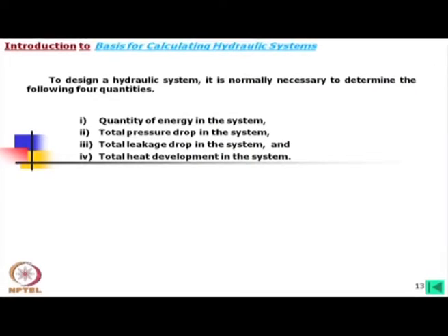Usually, while we are thinking of any transmission system, we should look into efficiency because that is most important. Unfortunately, a fluid power system has lower efficiency than pure mechanical or even electrical systems. The question is, why do we still use fluid power? It has many other advantages, because particularly you can handle a huge load with a small overall system size.